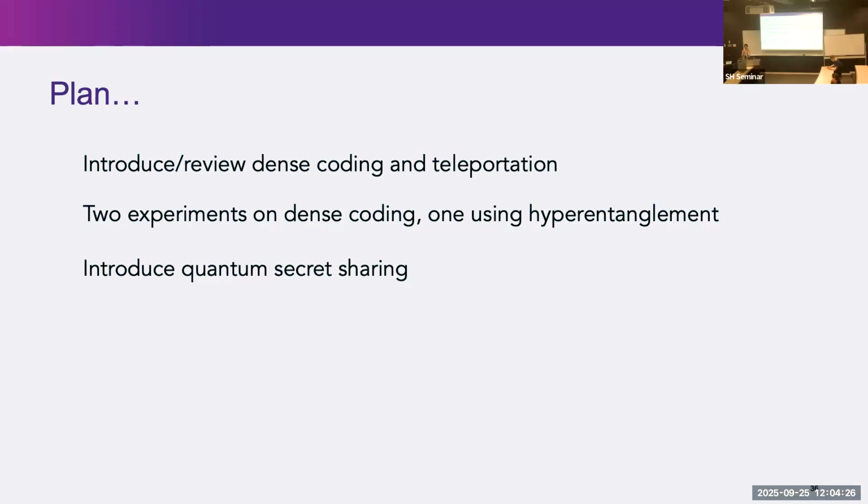So I kind of feel like it's cheating if I compare this small device to a longer device, right? In terms of loss, but if you're talking about performance like transmission and crosstalk, for example, which is important for multiplexers, we are approaching, if not better in some cases, what you design from the bottom up, like those techniques where you actually define the width of the waveguide, the bend, the distance between the waveguides.